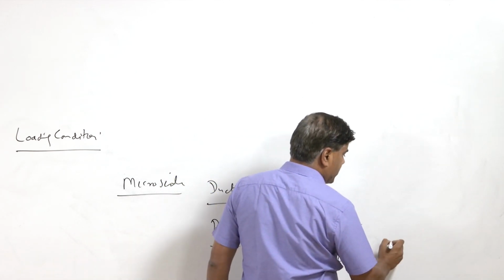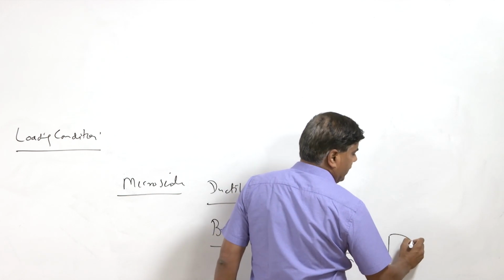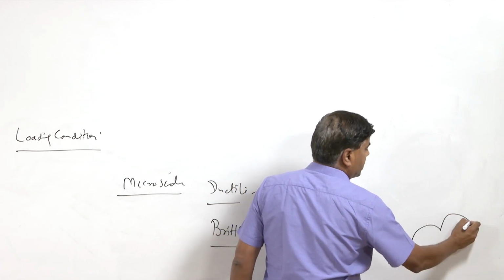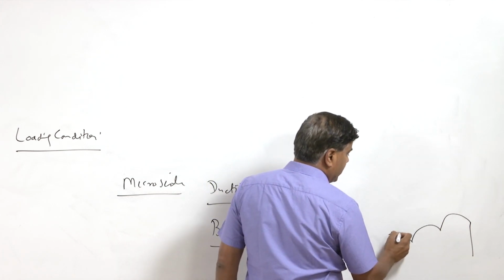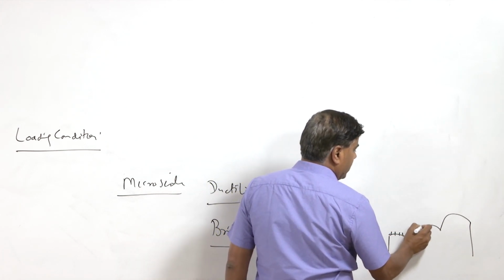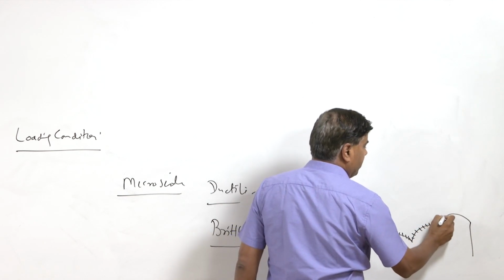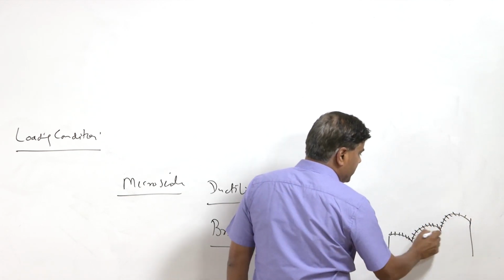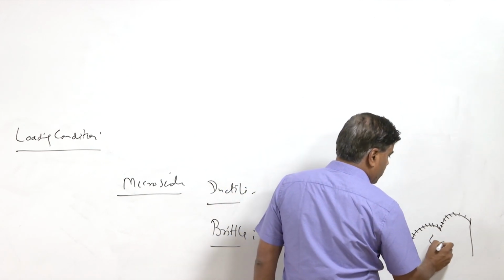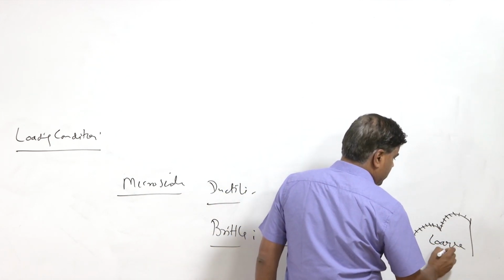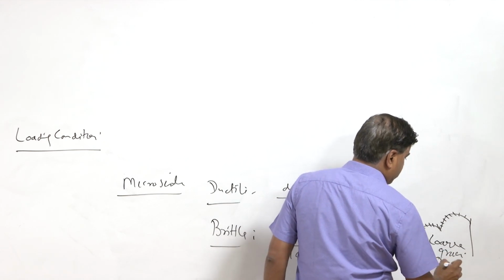Intergranular fracture shows ball shaped surface features, especially when the large grain size is there. The failure in this case occurs with the growth of the crack along the grains, and that is why each grain appears like a ball, especially when the component has a coarse grain size.